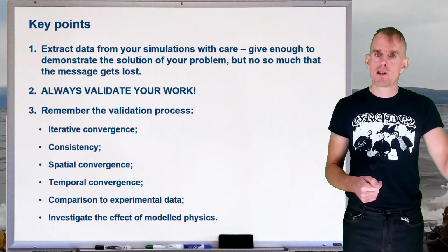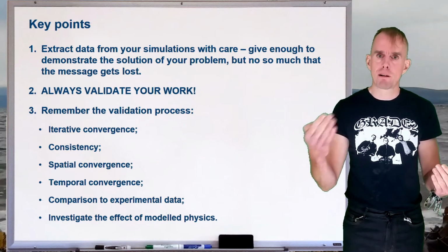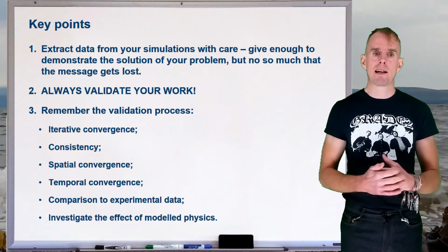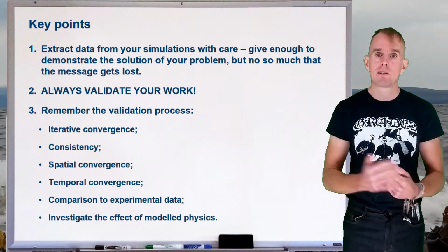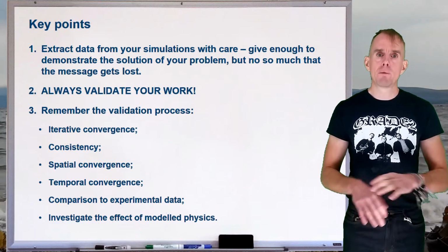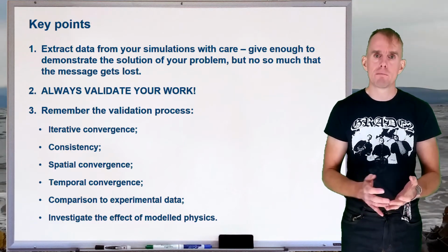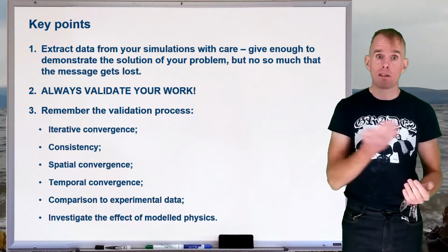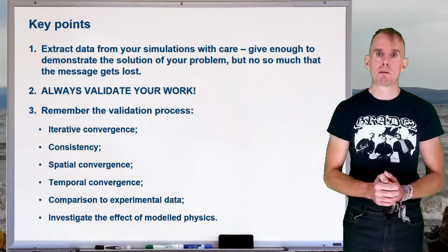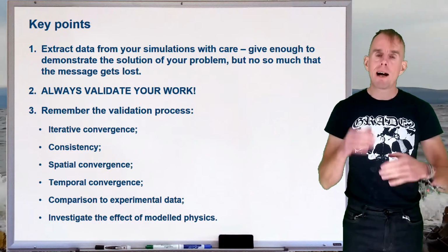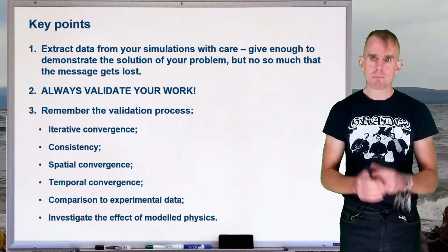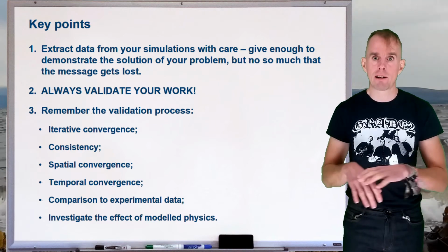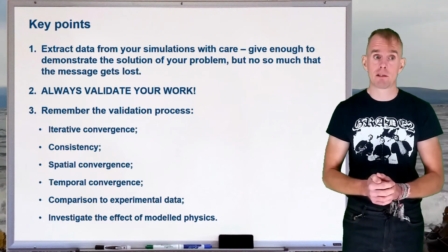Does the simulation bear any reality to experimental data? For the purposes of this course, we're going to be looking at use of analytical models and data from literature. If, however, you were doing a CFD campaign for a project, you may well have a parallel experimental program to give validation data. And when we talked about that experimental program, don't forget that you start simple and then build up to increasing complexity. The first experiment you should do should be incredibly well controlled, such that there is very little uncertainty in the experimental data.